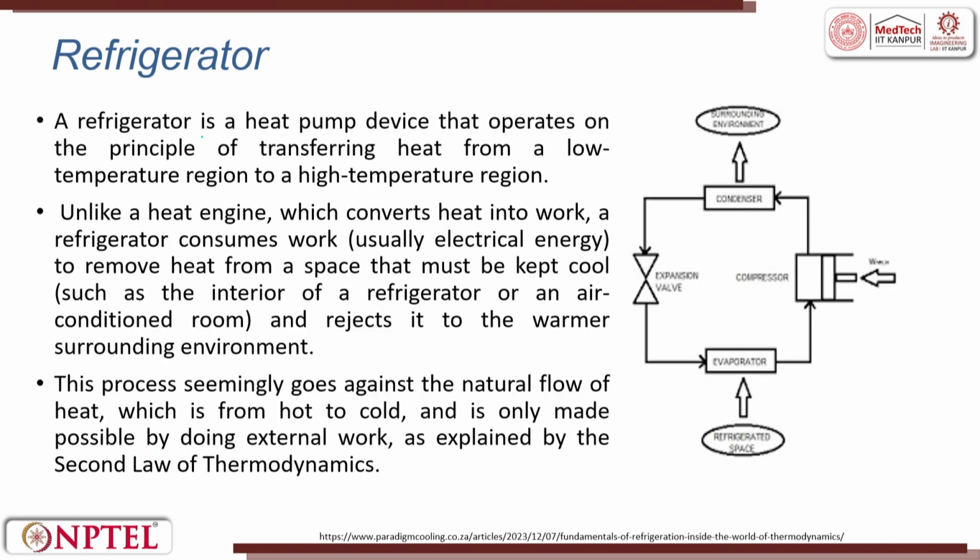The refrigerator is a heat pump device that operates on the principle of transferring heat from a lower temperature region to a higher temperature region. Unlike heat engines, which convert heat into work, a refrigerator consumes work to remove heat from the space that must be kept cool and reject it to the warmer surrounding environment.